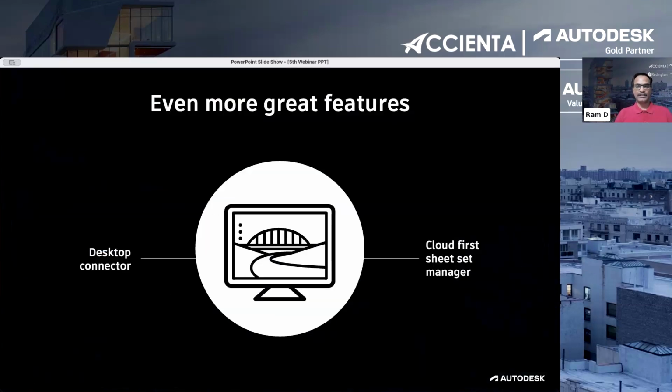Fantastic. So this is what I was telling about. You have a lot of data placed in your desktop, and you can't just copy it and put it into the cloud. So how do you make sure you connect Civil 3D to the cloud application? There is a connector called the desktop connector. Desktop connector is another application which needs to be installed, so that you have Civil 3D as software installed, and the desktop connector as an application you have to install.